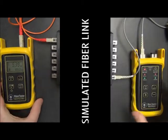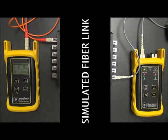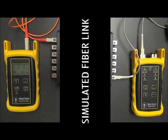Once you connect in with the WaveTester, make sure that you let the WaveTester go through a cycle or two of 850 and 1300. What that means is that by doing so, it allows the meter to have acquired both loss measurements on the screen. So we've let it do that.